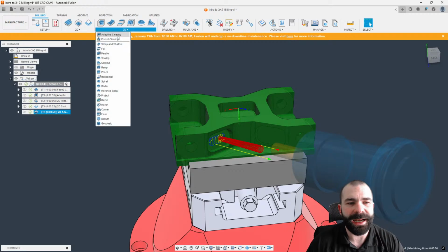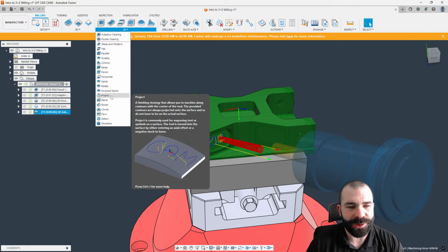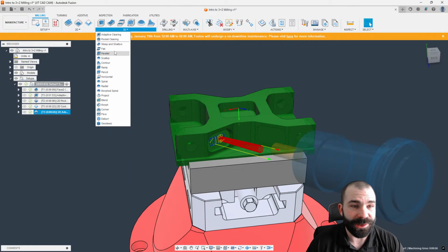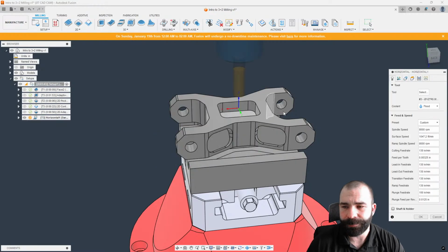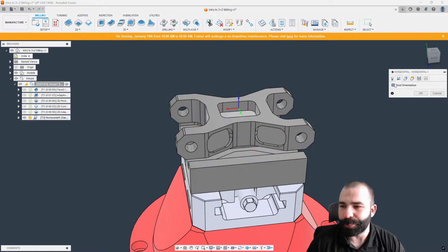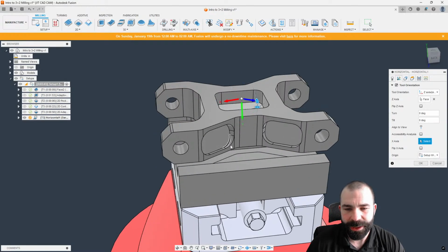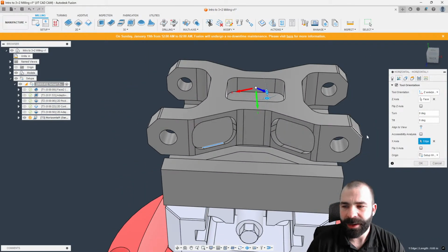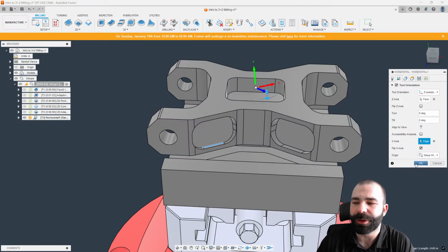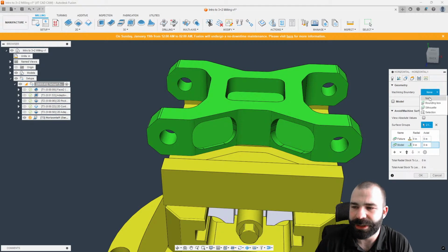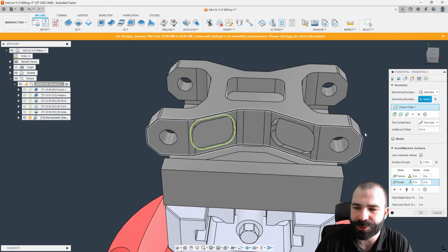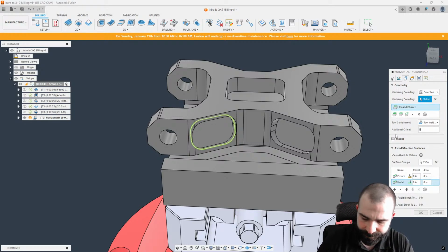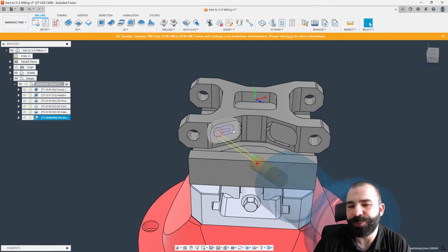Well, again, I would go back and do my 2D, actually not 2D, I apologize. We're going to go for horizontal. This time I'm going to make it a little more of a pain. We're going to say Z this way, maybe X this way. I do need to flip my X axis. And what you're noticing is the amount of clicks I'm starting to do here. Again, we're going to give this a boundary real quick. Pull inside that area, nothing extra. And as you're going to see, we're now finishing that floor, right?